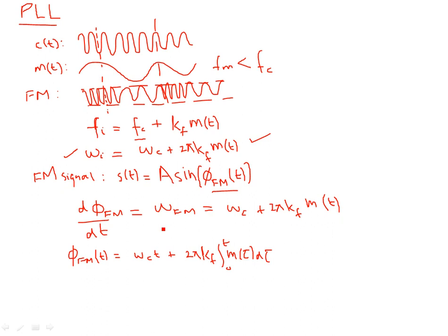So you can see the phase and the frequency are very closely related, and they're related by the differential. So it just implies that if you are going to vary one quantity, frequency, which is being varied with respect to the frequency of your incoming message signal, it doesn't mean that the phase is not being varied. Well, phase is also very closely related to the frequency. So these modulation schemes are sometimes called angle modulation schemes. Okay, so phase and FM are closely related, and they're known as angle modulation schemes.